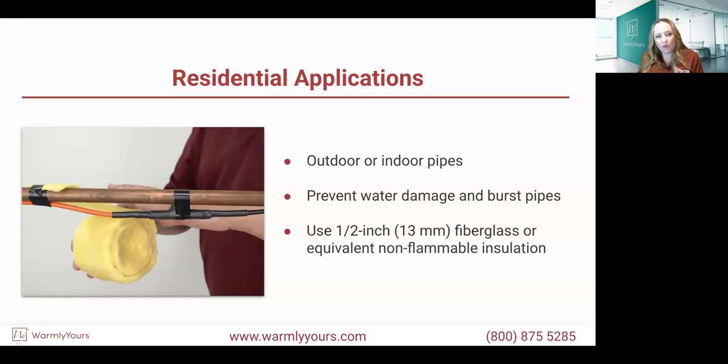Another thing, with the old school method, people used to think pipe trace was wrapped around the pipe. That's what I always thought, years and years ago. And so we got smarter and realized it just needs to go along the edge of the pipe so that it's melting at the lowest point, where the liquid would be in the pipe.